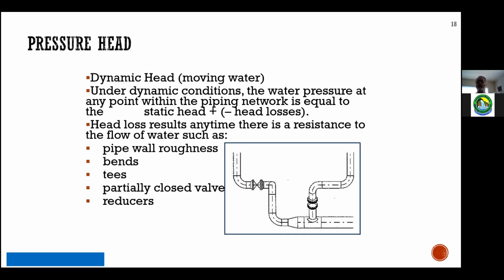but there were several times when these larger properties got developed and the customer, from the road to the house, was so far back from the road, ran too small a service line, and this was a long time ago, so they were using 1/2-inch soft copper. And by the time the plumber hooked up at the side of the road where our curb stop was left, by the time the plumber got to the house, there was basically a trickle of water left.